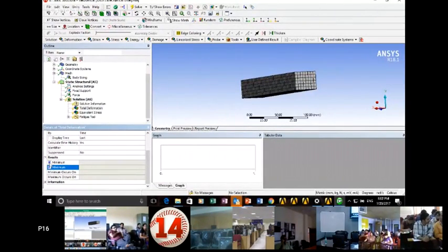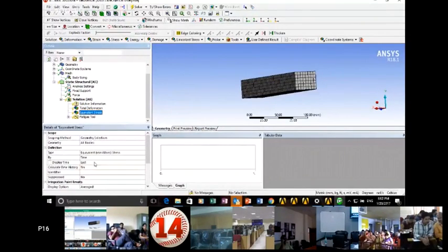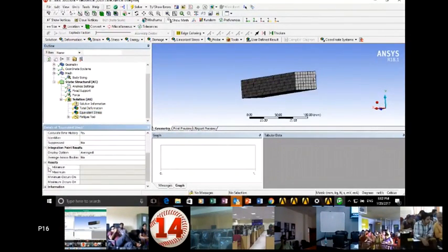You just have to click on that, check that box where the P has appeared, which means parameterization. Similarly, we will parameterize the value of equivalent stresses also to check the maximum and minimum value. Now we'll simply solve this model.